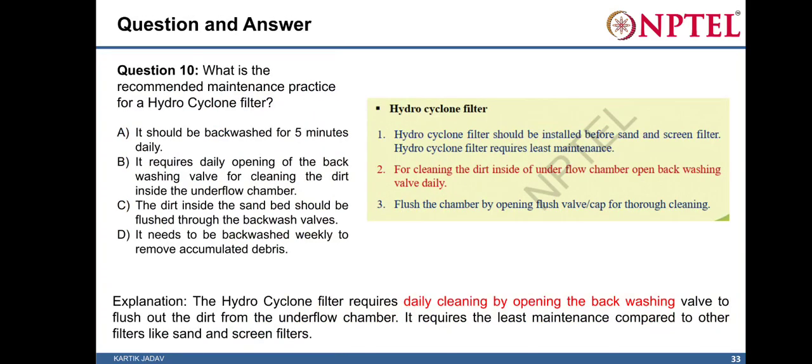Question number 10. What is the recommended maintenance practice of a hydrocyclone filter? So we know that a hydrocyclone filter requires daily opening of the backwashing valve for cleaning the dirt inside the chamber. Apart from that, the hydrocyclone filter should be installed before the sand and screen filter, and for cleaning the dirt inside the flow chamber, opening the backwashing valve daily is a fundamental requirement. And flush the chamber by opening the flush valve or cap for cleaning. So the correct answer is option B.